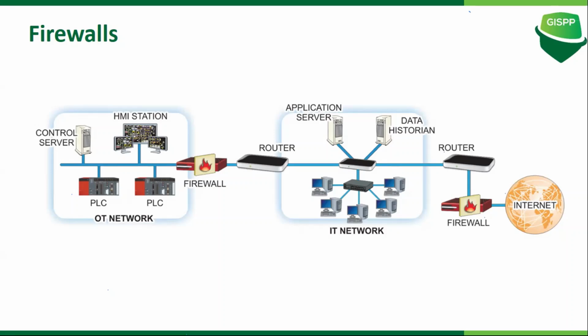So if I access the data historian server inside the ICS, then a lot of applications will be going inside ICS and taking that data. So what I will do, I will take out that data historian server. I will either put it in the IT network, which is also risky, or I will create a DMZ. So any guy who needs to access the data historian server should not go inside the ICS network and can access that data from the outside.